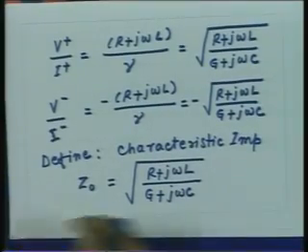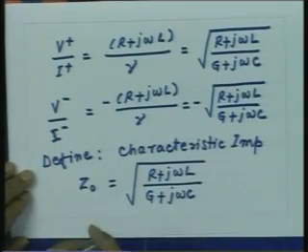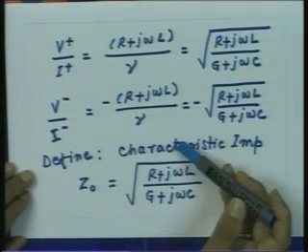Since we have an energy source at the left, it is equivalent to saying that there is something on the right side which is supplying energy to the energy source on the left side. So, the backward wave essentially is like an energy source supplying energy to the generator, that is equivalent to a negative resistance. So, here negative resistance is not in the conventional sense, it essentially is a manifestation of the direction of the energy flow on the transmission line.